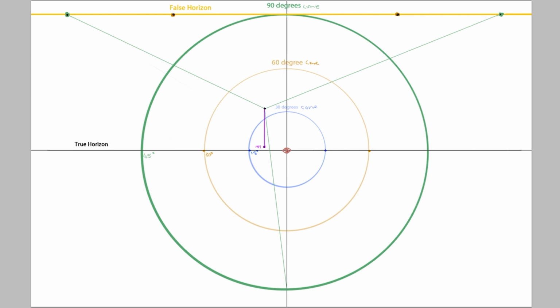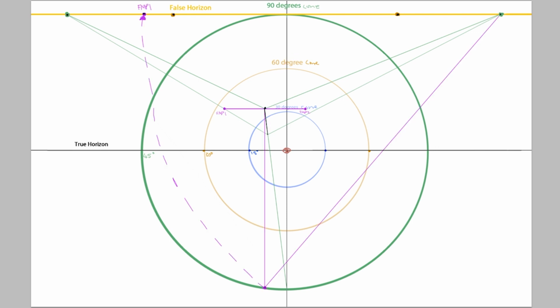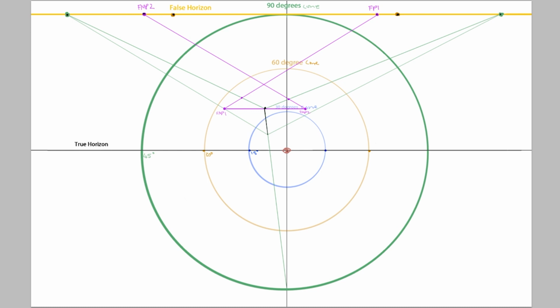So we're going to have to draw lines in the flat and then project them back into space to get our proportionate cube. In the same way we got the tilted square cube, we're going to find our first line of our 3-point cube by transferring the line to the vertical axis and tracing the line back to the vanishing point. We discover our first vertical line of our 3-point cube. Repeating this process for the 2 vertical lines on the new false horizon for both sides, and then tracing it back, we find our 2 vertical distances.